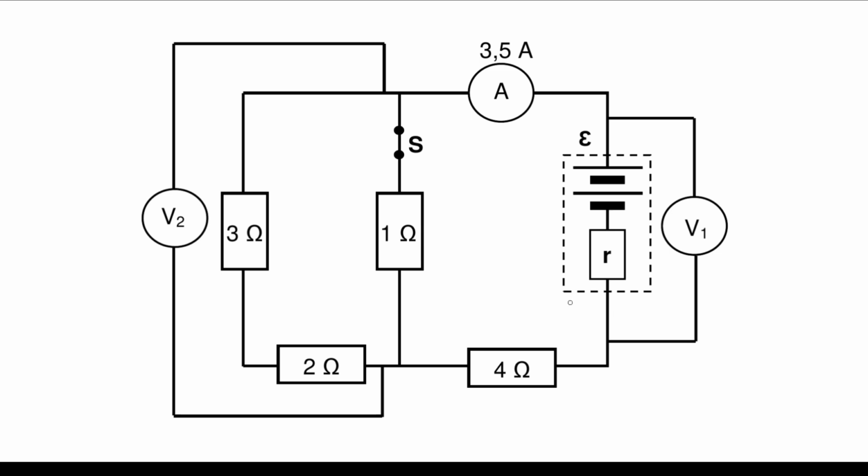What you do is you grab your pencil and you find the battery on your diagram. It doesn't matter what end of the battery you pick. I'm just going to pick the bottom one because I feel like it. Now we drag our pencil along the conducting wire until we get to a point where it splits. Now we look at what happens in the split. It ends in a voltmeter, and rule number 1 is no current through a voltmeter. So the current does not go down there. It follows on and hits a resistor, no problem.